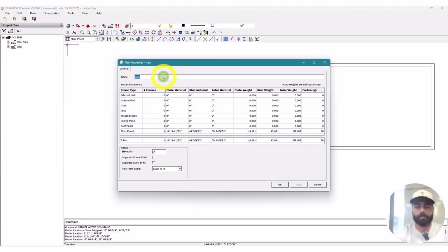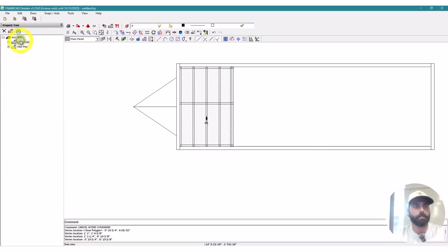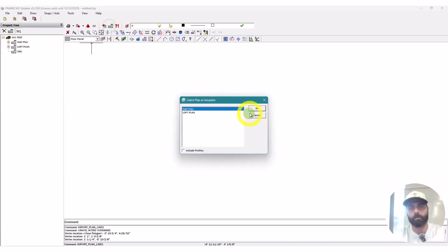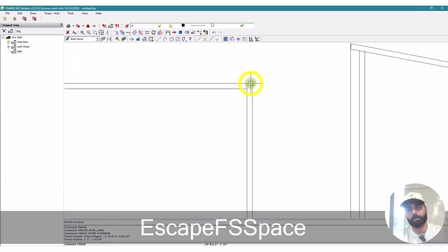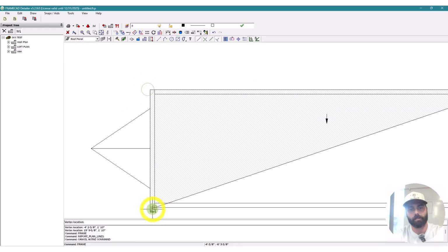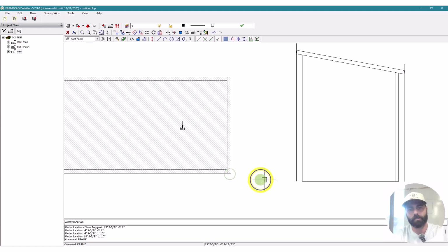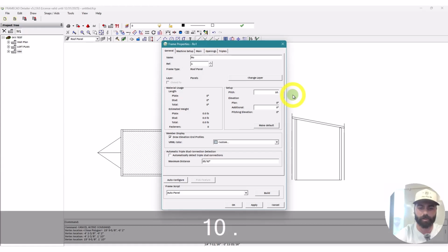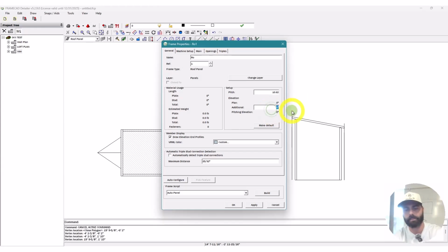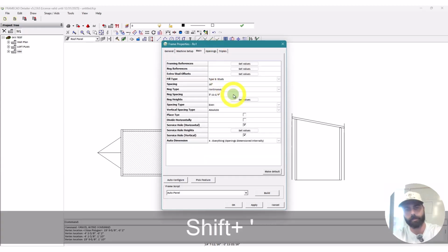And then we can go ahead and copy that wall plan again. And then we can design the roof. Let's see, roof panel. Properties, so we know that this is a 10.62. That starts 9 feet off the ground. And we go to main, we'll want 16-inch stud spacing. We'll do 4-foot nogging for your sheathing. Oh, we said we're doing a 6-inch roof panel, or 6-inch overhang. So I'm going to offset this by 6 inches.